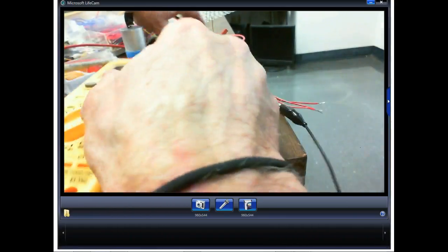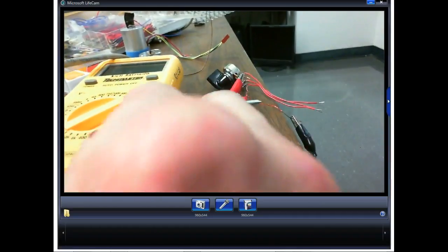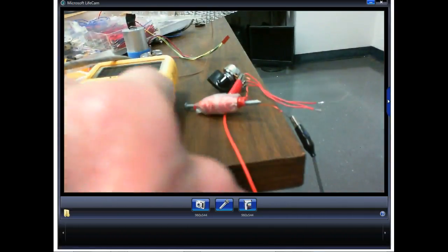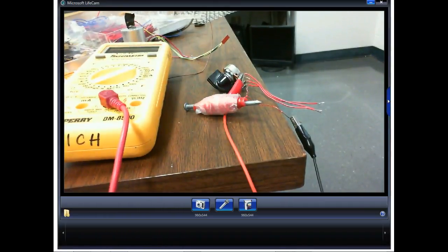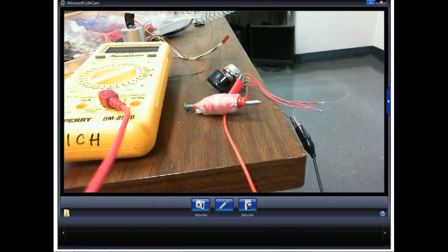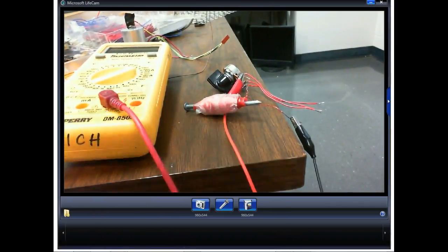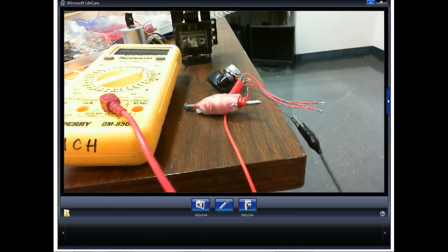What happened to my lead? So, by the way, you can't check this with a regular ohm meter, and we call it an ohm meter, even though it's going to display in volts. But just about every one of your newer meters has the ability to check diodes. It actually checks what we call a p-n junction. So you can use this to check all kinds of things.